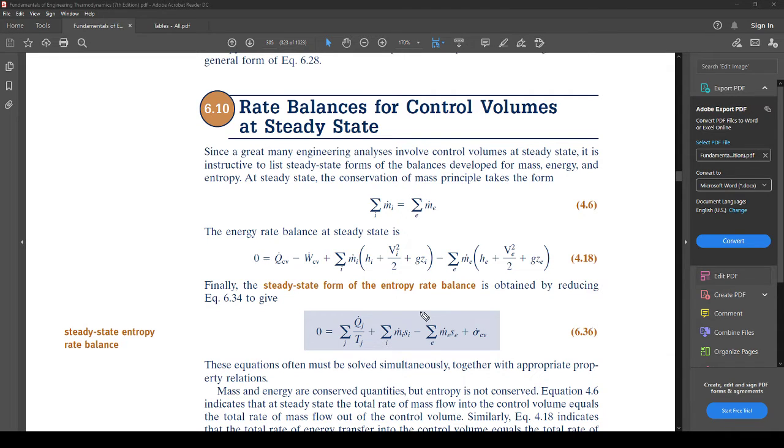That's fine. Steady state, if you guys recall, means no change with time. And so, this right here represented the change of entropy with respect to time. So since there's no change of entropy with time, it operates the same way from second 0 to second 100 or 1,000 or 1 million. This goes to 0. So that's why it takes on the form of this right here.